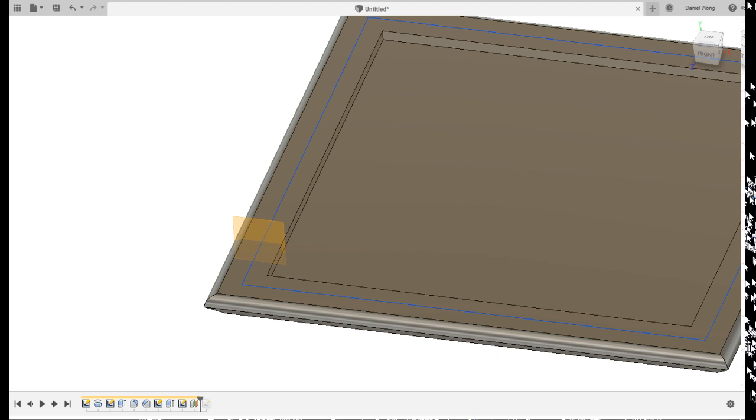Then I can reproduce the sketch in the timeline, and then I can redefine it onto this plane here. Okay, so that's what I've done there. Do you want me to repeat it one last time? Yes? I got one yes, that's good enough.